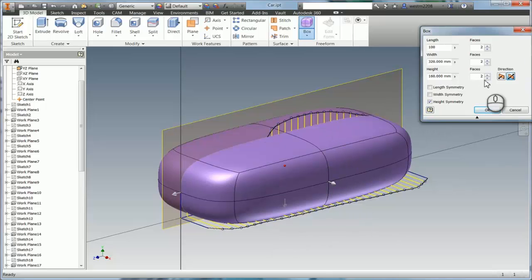You can also do it afterwards in edit form for a unique operation. For example, before you move one of the parts, you can say, all right, now for this one move, do it symmetrically. So if your part is always going to be symmetrical, you can do it here and it's much quicker. However, if you don't want that, then don't add symmetry here, just add it in for the operation where you need it. The other thing you can do is along here you've got faces.